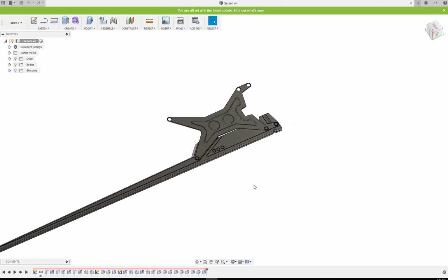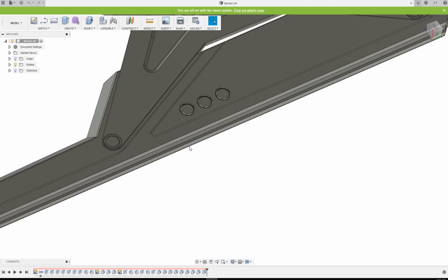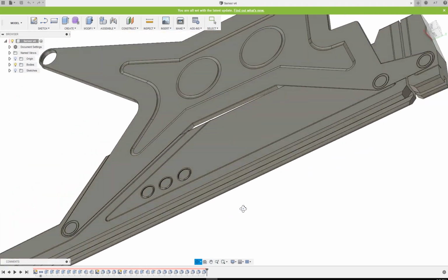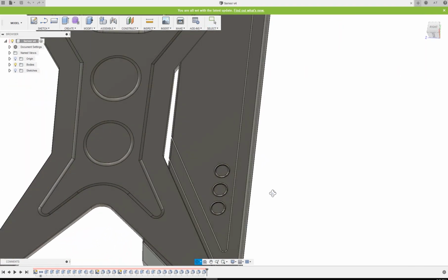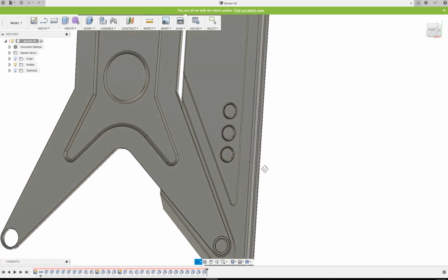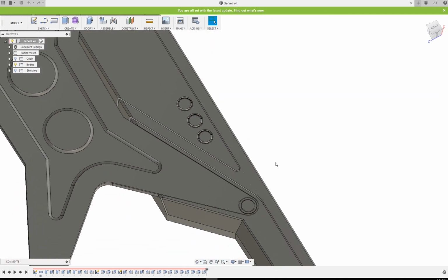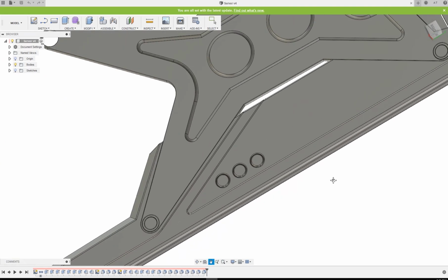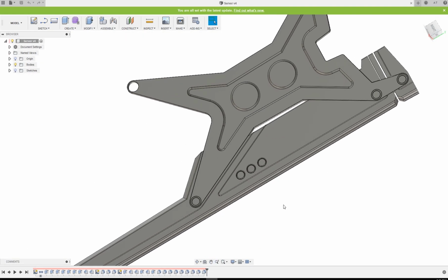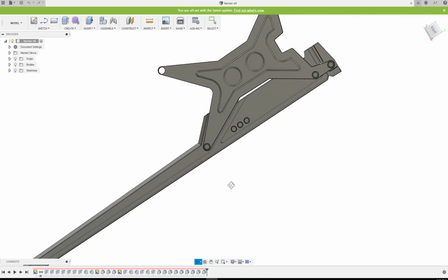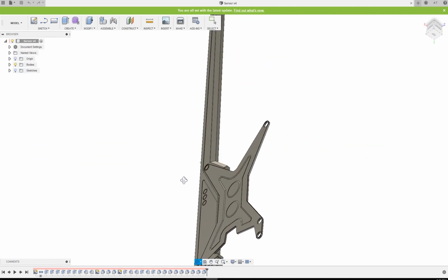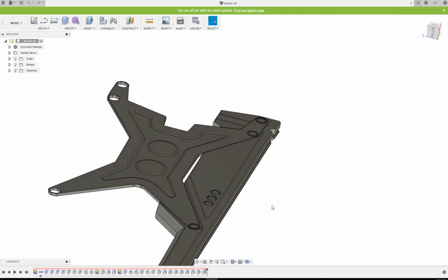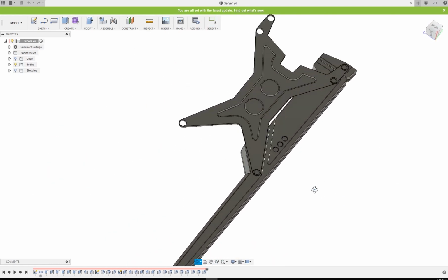One thing I didn't do in Fusion was fillet all the edges, which kind of beat me in the end. I didn't do it because I knew that KeyShot has a pretty decent Round Edges shader there, which rounds all the edges you input. I did it on the vertex drone, which did a good job. However, my scene was so heavy that when I was inside the scene, it was really tough to edit anything, and I didn't like the Round Edges shader applied to it. It just crashed the whole scene.